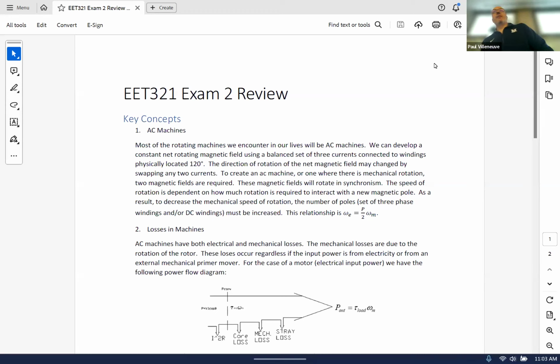Okay, so feel free to interrupt and ask questions about any of the material, and we'll go from there. This is the first time that we talked about rotating a machine. We do have phasors, voltages and currents, that rotate, right? That's the sine wave, but we always do things in steady state. So in AC circuit analysis, we assume that the rotation is non-existent, even though it is actually happening. We don't need it to do any of the calculations. And so we do snapshots in time, and then we do things from a consistent steady state standpoint.